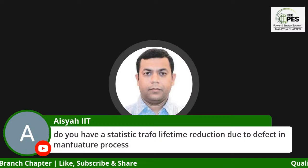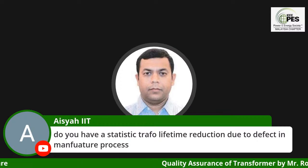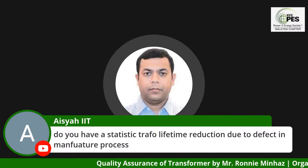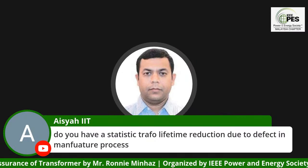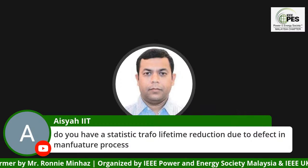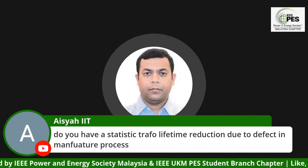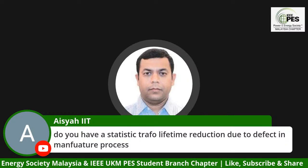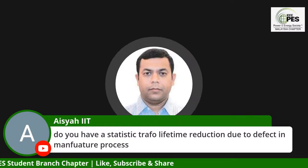When the polymerization increases, the paper loses its tensile strength, it loses its dielectric strength, and it loses the life of the transformer. So there is no statistics like this. I'm not aware of any statistics, but what I brought to you in this presentation, we never thought of that way before, but we need to think about that.